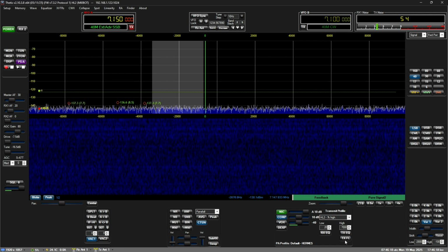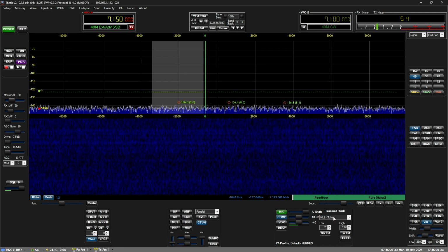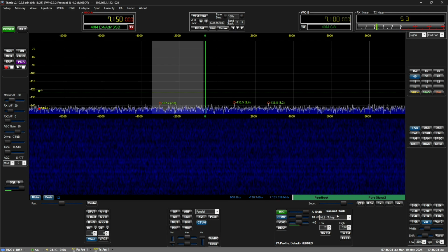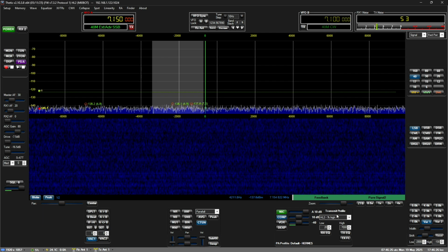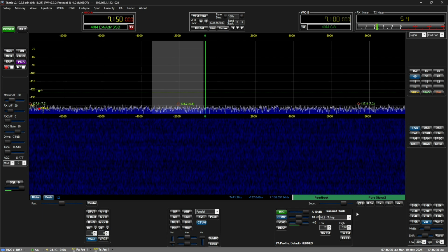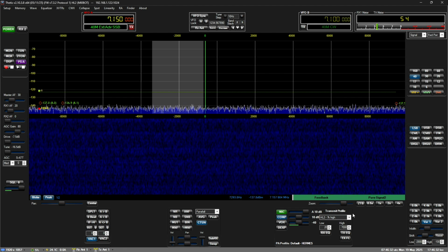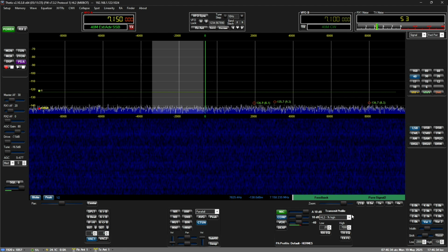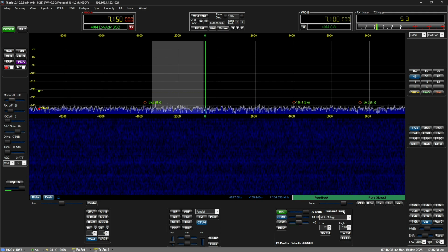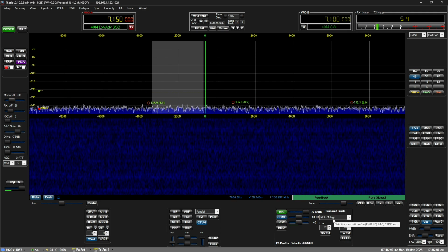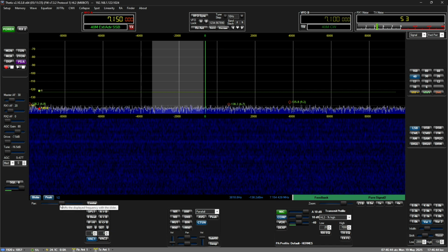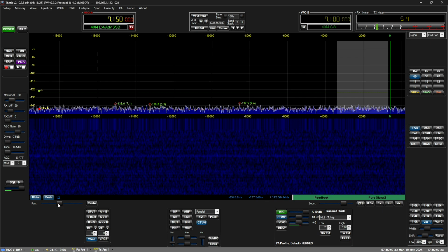My profile at the moment, I've got it set to 7K. I know that there's some people that are interested in extended sideband, and I think legally we're allowed to use up to 8 kilohertz. That's pretty wide. So this profile at the moment is set for 7K. I thought that's appropriate, just to test the microphone on it, just to see how it actually modulates right across.